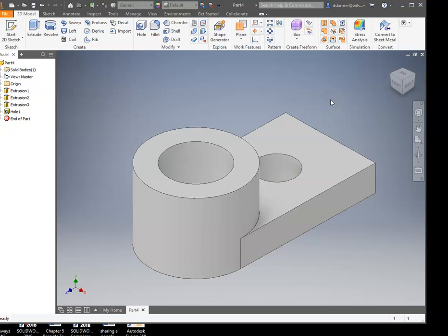If I wanted to change those dimensions, I would have to go into the feature, and you can see if I left click on the arrow, it actually has created a sketch for me, but I didn't have to select that sketch. Looking at this, maybe I want to orbit around, just to be sure that hole goes all the way through.